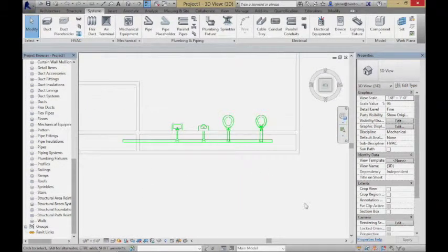I'd like to run some hot and cold water pipes in that wall also. The hot and cold water pipes I could put low, I could put high. The nice thing is they can be at almost any level because they are pressurized, just really wherever we can physically run them so that they're not interfering with too much. I'll put them higher so that they're not getting in the way of that sewage pipe, the sanitary pipe, as it's moving along. So let's place some pipes there.